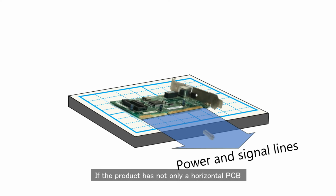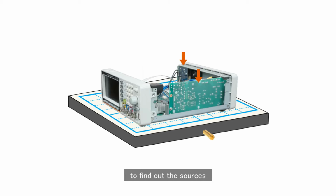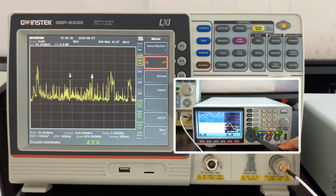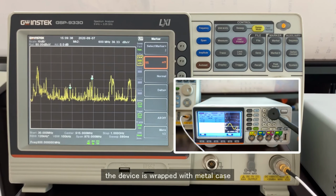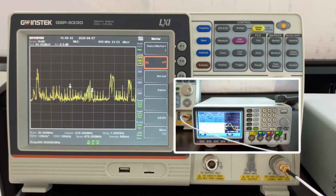If the product has not only a horizontal PC board, but also a vertical one, a piled one, or the one located in a finished product, then it's not that easy for EM scanner to find out the source. Just like our example for today, the device is wrapped with metal case. The EMI is leaked from the gaps, then we have to use the probe.